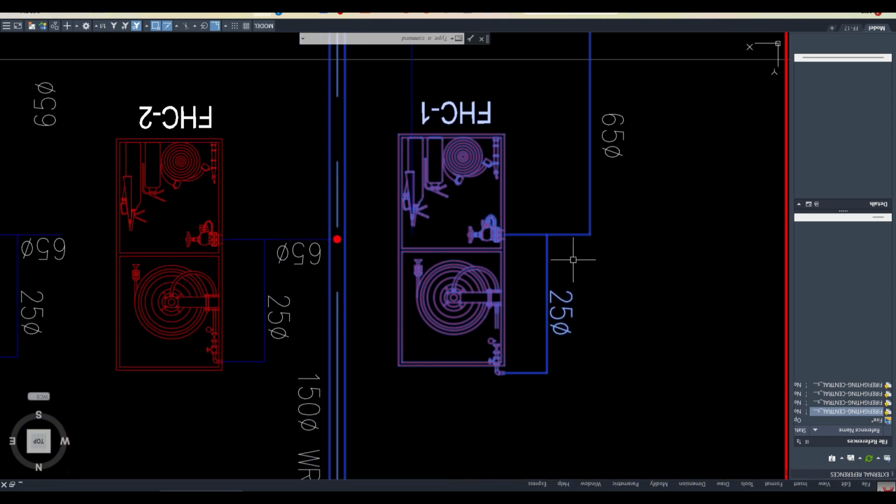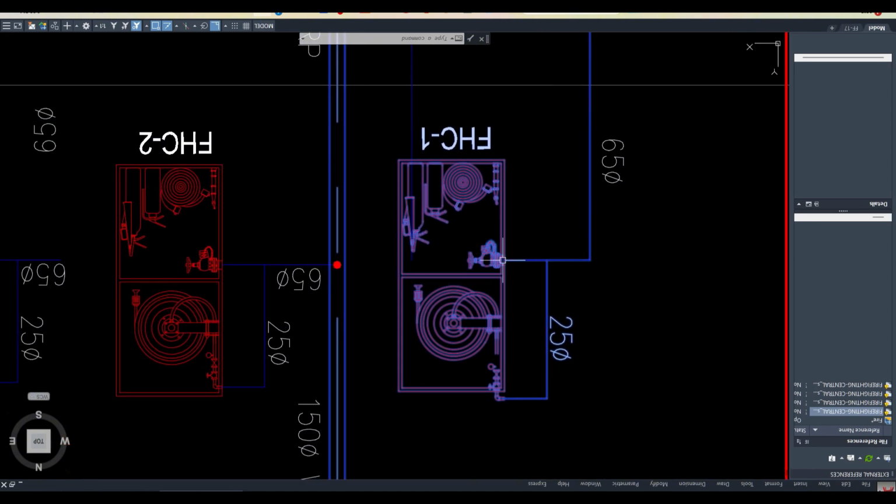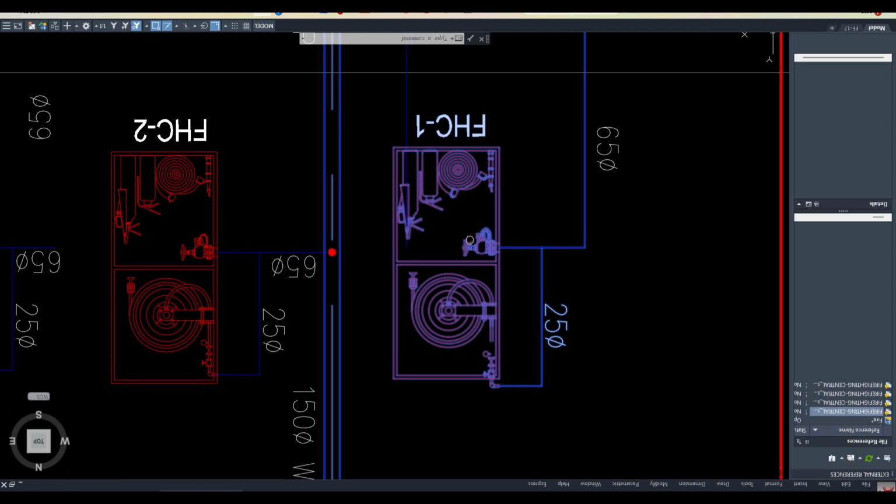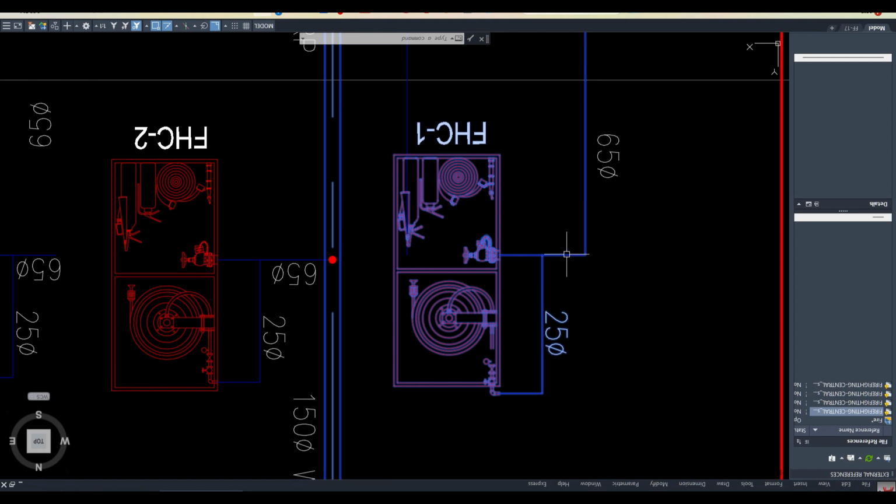So how do you do it? The same pipe is connected here, and this system requires a minimum of 6.9 bar, and from the same pipe they are giving connections to this system which requires not more than 4.5 bar, so how will they make this connection? It means this will also deliver the same pressure, right?